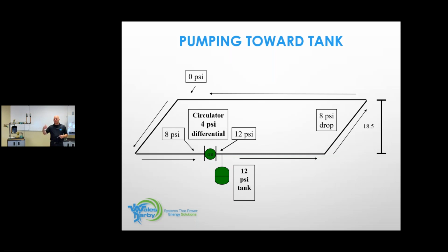Historically, you're going there 2 times a year to purge air out. Take a look at the piping. Take a look at the circulator location. If it is on the return, don't go in there and say, oh my God, we've got to repipe this whole system. Maybe you can remove the expansion tank and elevate the pressures within the system.